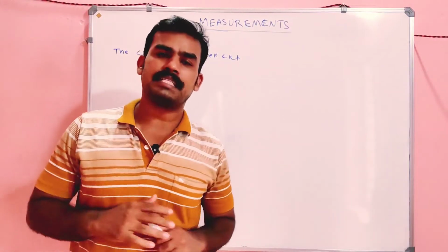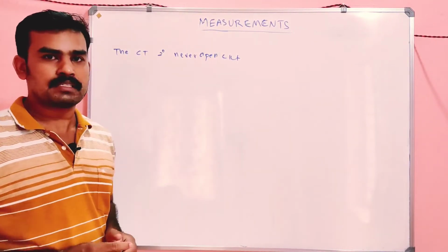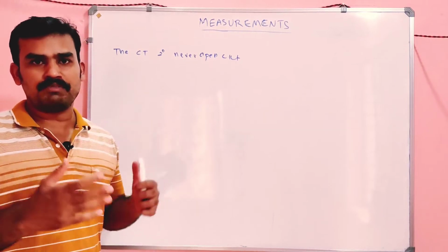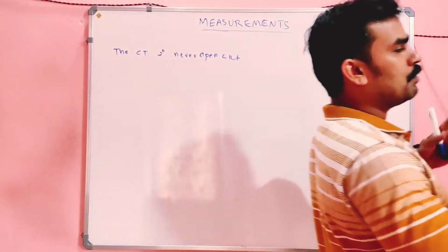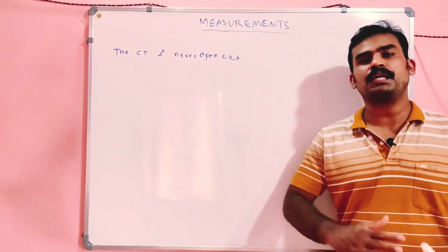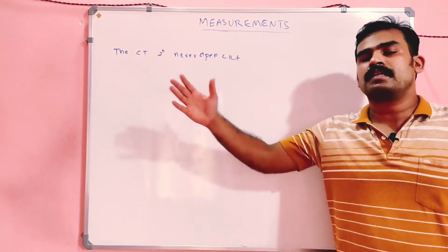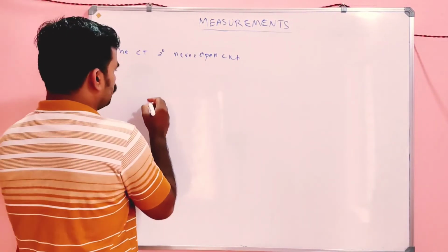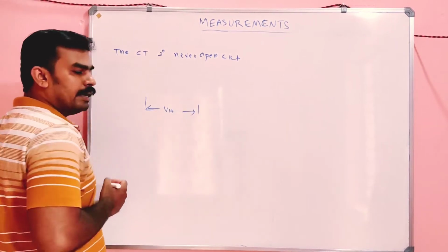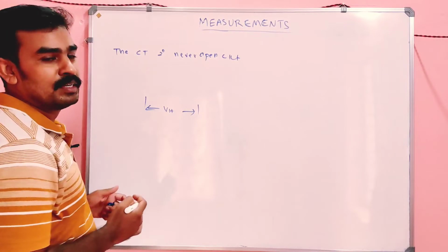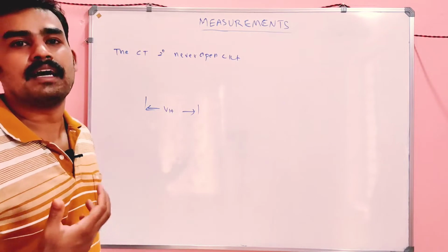In a current transformer, the secondary winding has a huge number of turns, which means a large induced EMF or voltage will be developed, because the voltage is directly proportional to the number of turns. If the number of turns increases, a huge voltage will be generated in the secondary, in the kilovolt range it may be. So if it is open circuit, across the terminal a huge voltage is expected to appear. So someone standing nearby may definitely get a shock, which is a risk.